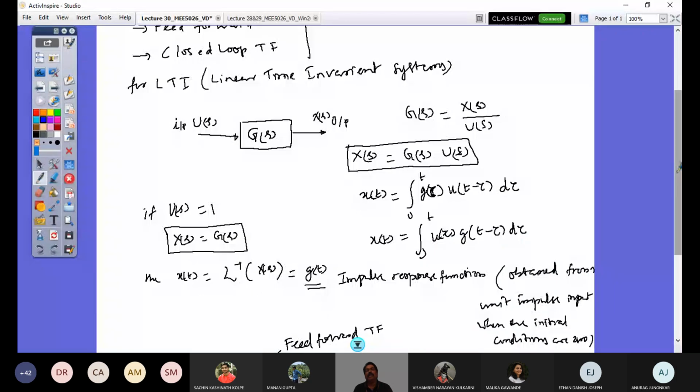What you get would be your transfer function, because when you give a pulse to your input, it may not be exactly a unit pulse input, but you would have some value, so you can get the equivalent of your unit pulse input. When I excite with a hammer, I'm not going to give exactly 1 Newton. It may be 2 Newton, 3 Newton force. Gently I will excite. Giving 1 Newton all the time is not possible, but it is a scaled value. So what I get would be my transfer function. So the first diagram drawn is an open loop system. You rightly said. So this is an open loop system.